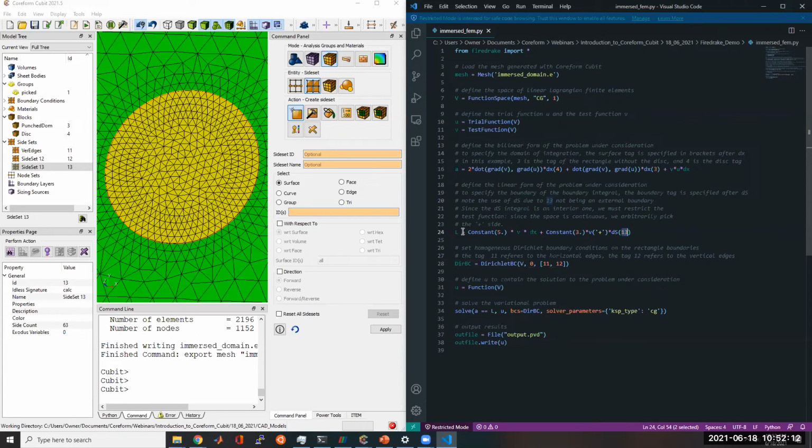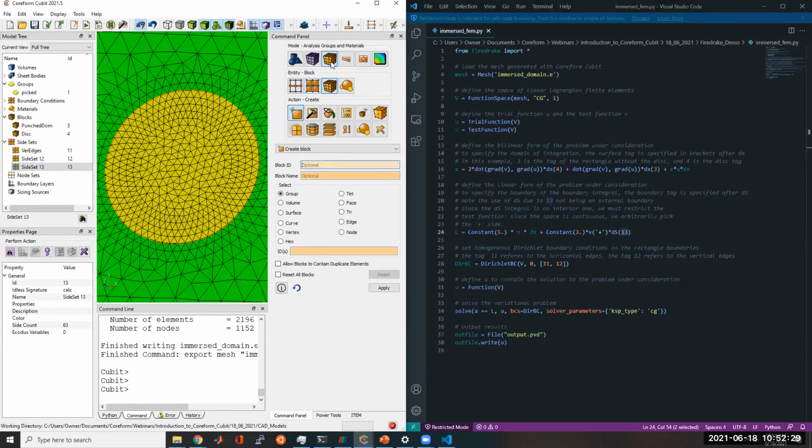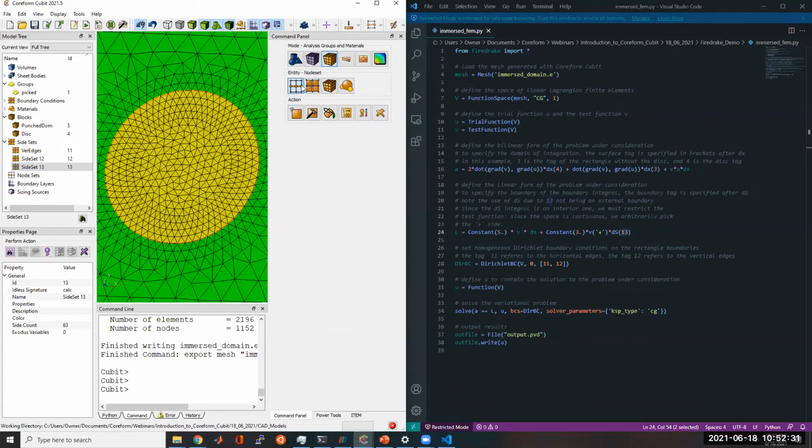Like in Abaqus, for instance, you have element sets, and there'll be a material card, and then a section card that applies a certain material to a certain set. And so you're going to define all of that through assigning these blocks, side sets, and node sets.